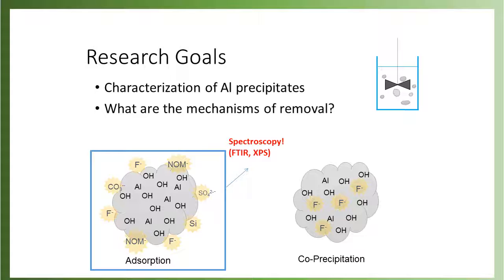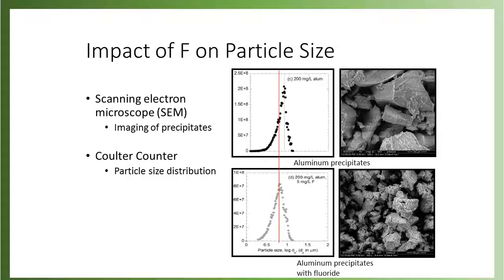It's also important to note that this process is very different from defined batch adsorption experiments that you see in the literature, mainly because the co-precipitation and the coagulation and everything is occurring simultaneously over the time period of a drinking water treatment plant, and thus there are many processes happening simultaneously with these amorphous solids that are not well characterized. So it's important to really understand what's happening here.